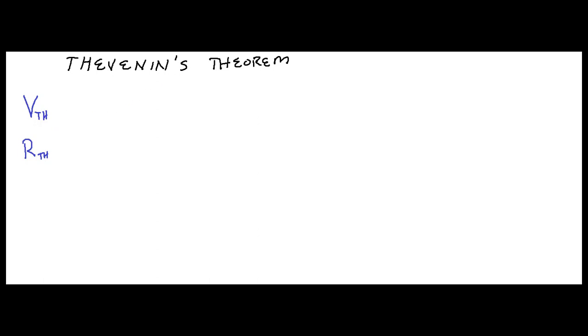And when you draw your equivalent circuit, you're basically going to have a source like this. This is going to be your VTH. That's an H there. I drew that a little fast, I'm sorry. And this part is going to be your RTH, your Thevenin resistance. And most times then between 2 points like this, you may have a resistor or something that goes in between here in your analysis. But they're in series, right? You have your Thevenin voltage, and then in series with it is your Thevenin resistance.